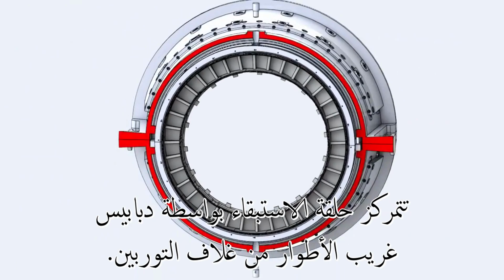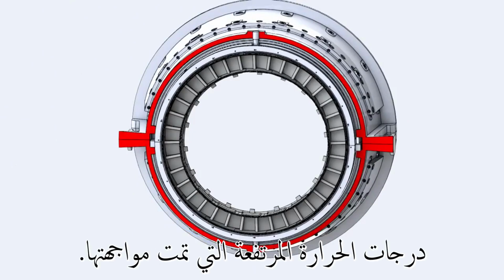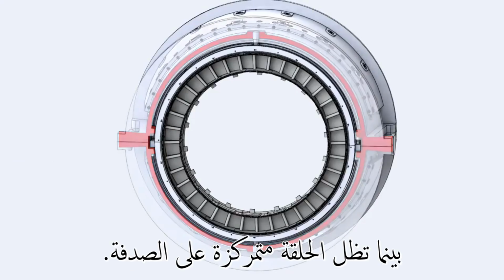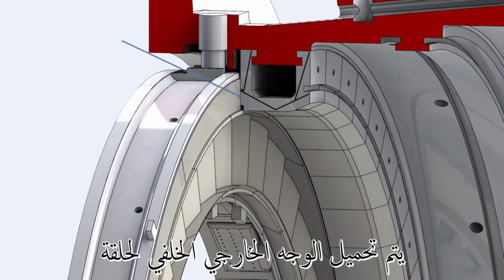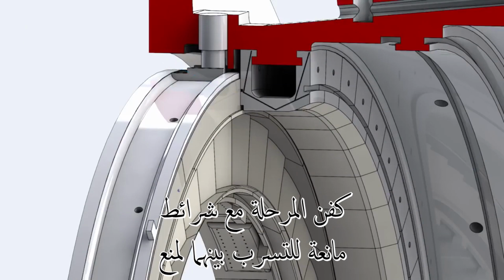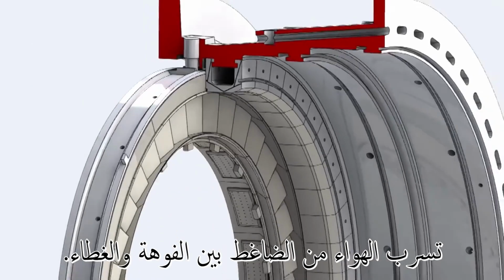The retaining ring is centered by 2 eccentric pins from the turbine shell. This configuration permits radial expansion due to the high temperatures encountered, while the ring remains centered to the shell. The aft outer face of the retaining ring is loaded against the forward face of the first stage shroud, with steel strips in between to prevent compressor discharge air leakage between the nozzle and the shell.